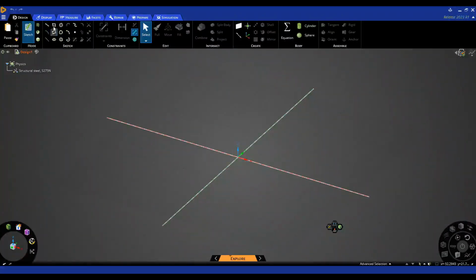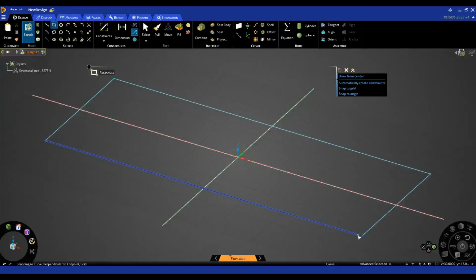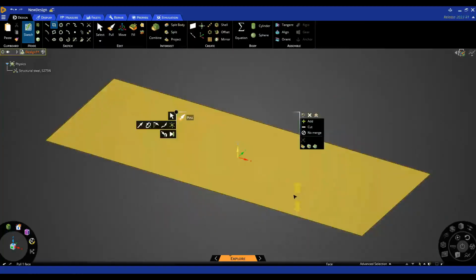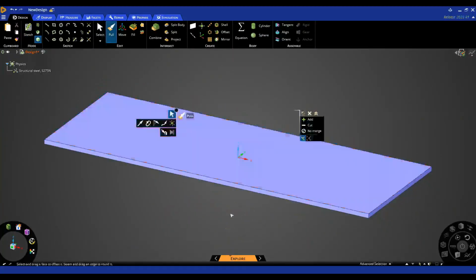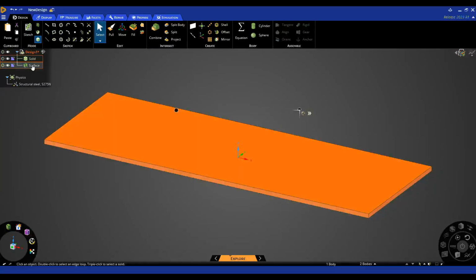So this is Discovery modeling. We're going to create a thin piece of geometry. Let's make it 80 by 30, and we'll create a fairly high aspect ratio part of just 1 millimeter in thickness. And if we want to add a film, I do Control C, Control V to create a surface on top of the solid. We can put this into a single component.